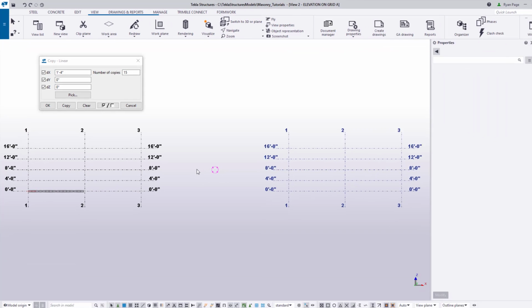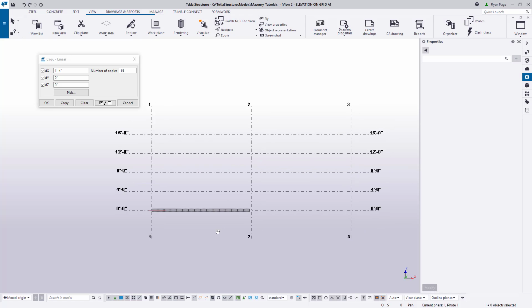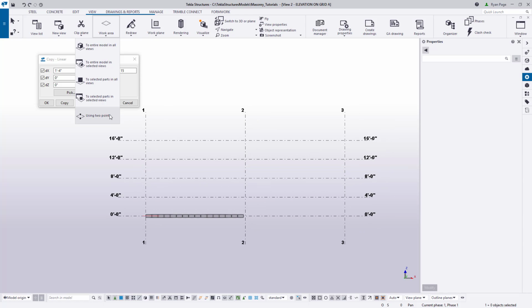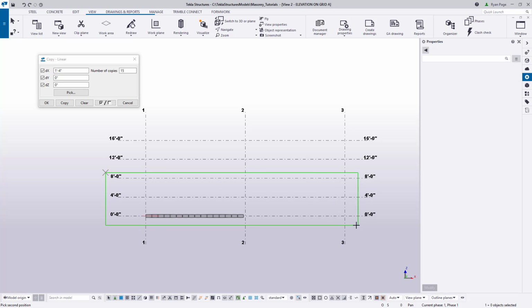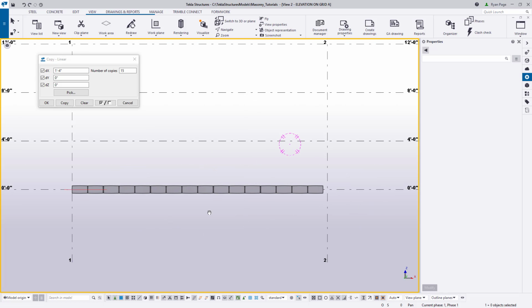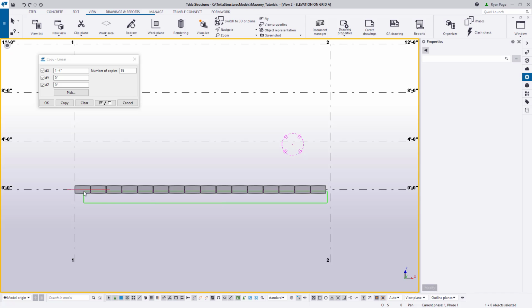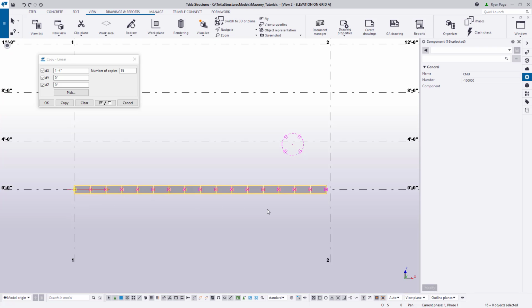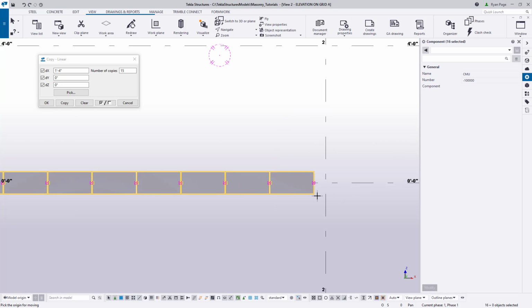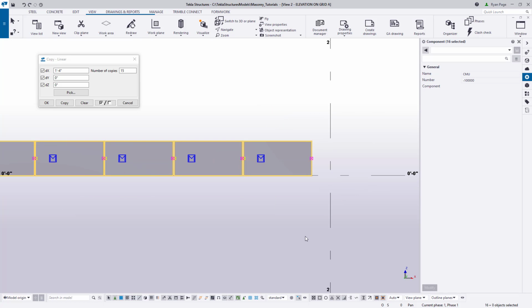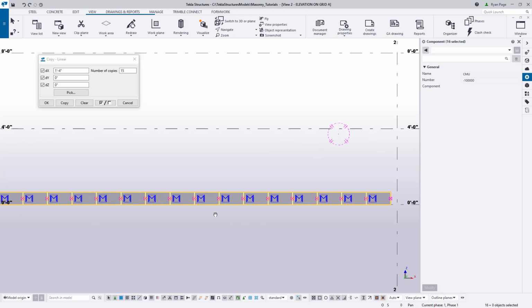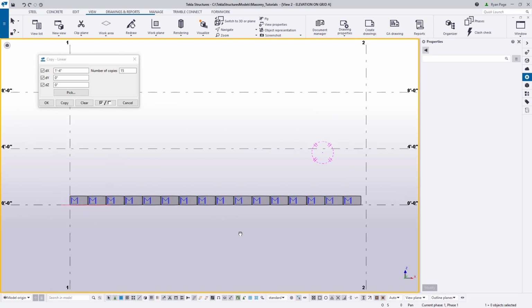From here, we'll go ahead and just shrink the work area by going to the Work Area dropdown, selecting by 2 points, and then picking an area that extends over the left grid. Next step, we want to raise these blocks so they sit at 0 elevation, so we'll select them all. Right-click and hit Move, and then we'll grab the bottom of the block and then just snap up to the grid or the 0'0" grid line.